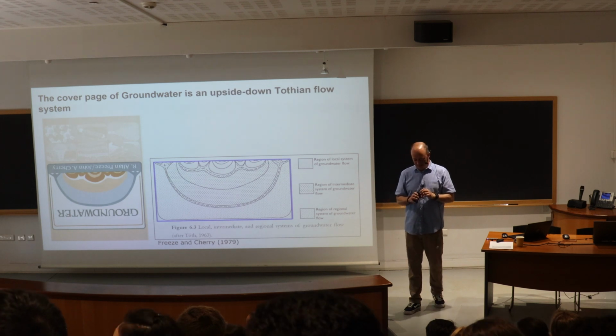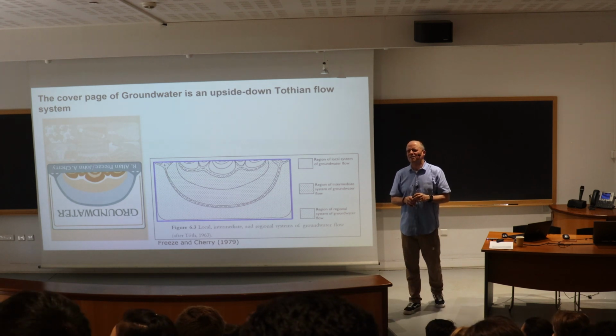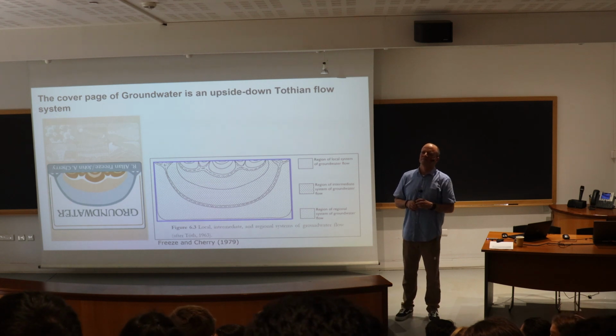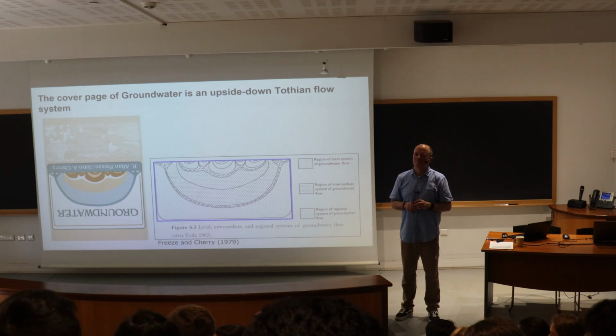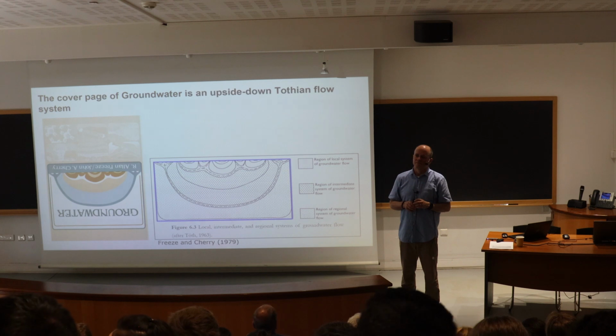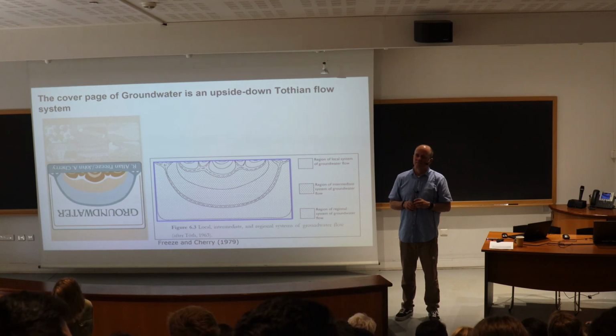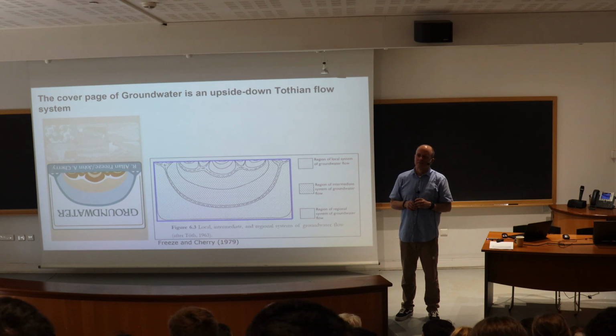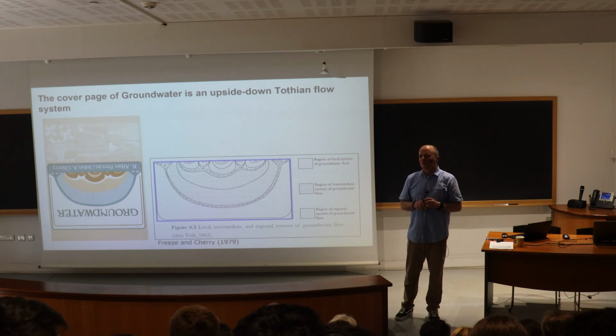The discussion is interesting. But when you're talking about REV, so let's say if there is a larger fracture, cannot we use Darcy-Brinkman there rather than just only Darcy? Because Darcy has some assumption about this REV, but if there are large fractures, their flow could literally be taken to the Brinkman term.